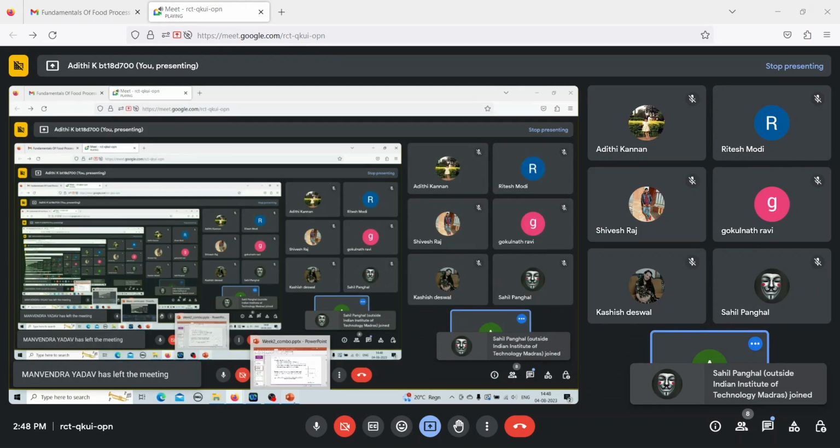Relaxation time in this particular part of the graph: you can see that the moment you drop the stress, the strain gradually decreases. The time where the strain is 36.8% of its initial value is known as the relaxation time. We'll discuss what relaxation time is in more detail in the upcoming slides. But as of now, what you need to know is that Deborah's number is relaxation time divided by time period of observation.